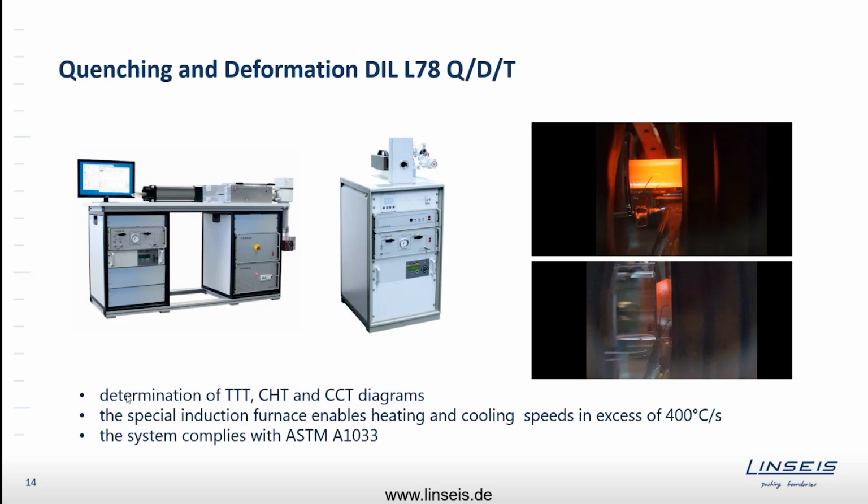As said, we reach rates up to 1000 centigrades per second heating and up to 400 centigrades per second cooling, which allows the creation of CCT, CHT, and TTT, so controlled temperature profiles, so 3D phase diagrams. This complies with the ASTM standard A1033, which is very, very special, and it's a steel industries standard.